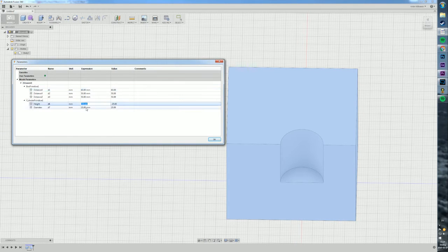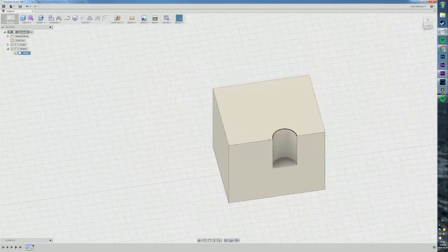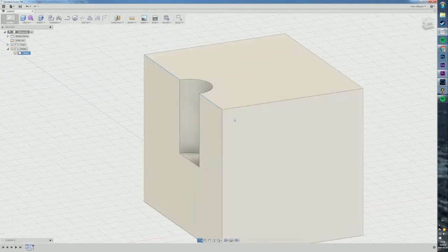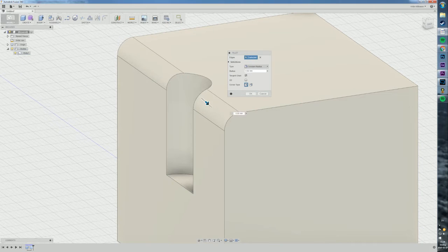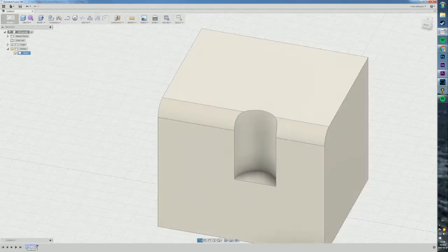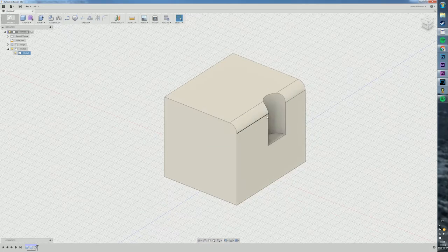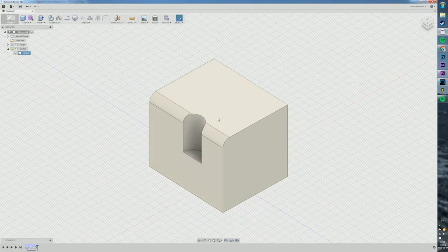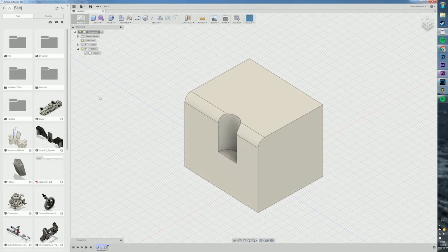And I can change here the diameter, I want to have it, let's say 15 instead. So I'm just making the hole smaller. By using solids and parametric solids, I can start to edit things much more clearly. And for example, just adding something like a little fillet is really tricky to do on, let's say, a polygon model. Usually you can do it on surface models as well, but that's really one of the strengths of the solid tools. So let's check out an example of how you can use the solid tools.